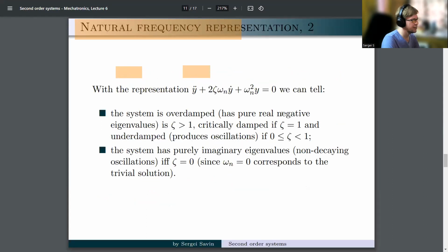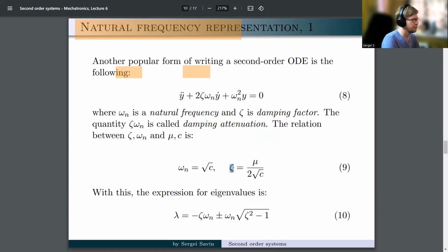Well, let's quickly go back and see that the damping factor is mu divided by 2c. So c would not be infinite, right? And the only way for this number to be 0 is for the numerator to be 0, right? This part of the ratio is not going to infinity, so mu has to be 0 for this to be 0.